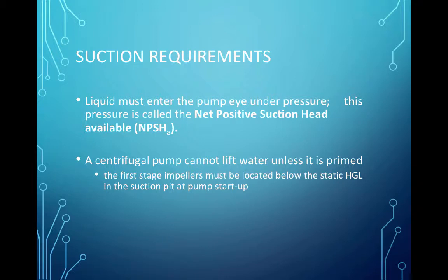You set everything up, you open the priming valve to release water into the suction tube, and you turn on the pump at the same time. And if all goes well, and sometimes it happens the first time, usually by the second, usually you have to prime them 1 or 2 times, and then the system is good to go. You close all the priming valves and you let the thing run. Then, once it's running like that, usually there's a discharge side valve.